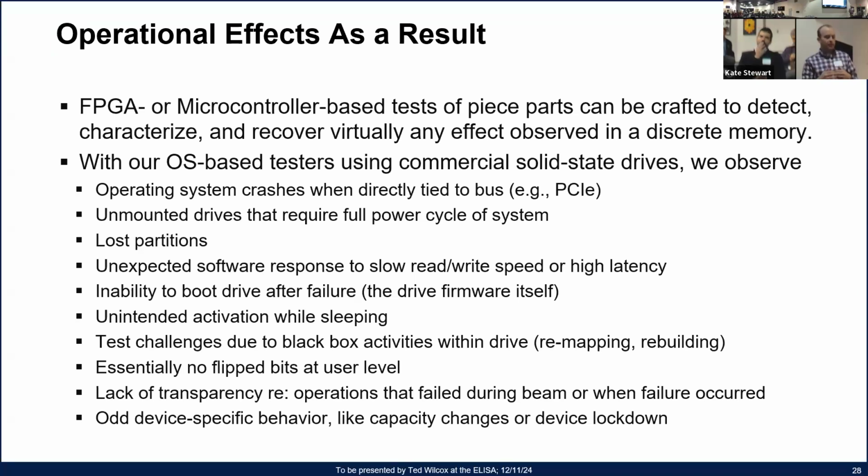So there's a few different folks working on that, but maybe on the next slide, one of the challenges with these devices is as we get more complex, in the past, if we'll use a voltage regulator as an example, you could find one that was good enough. With the piece part NAND flash, you can find the part that's good enough in most cases to apply it. You might have to do some testing and maybe some mitigation, but we can find something that just happens to be good enough serendipitously. That has not been the case with solid state drives, and there are numerous parties out there performing testing of commercially available drives, and really there is not one out there that is good enough to apply. So I'm still looking for that as the starting point for some of these system designs.